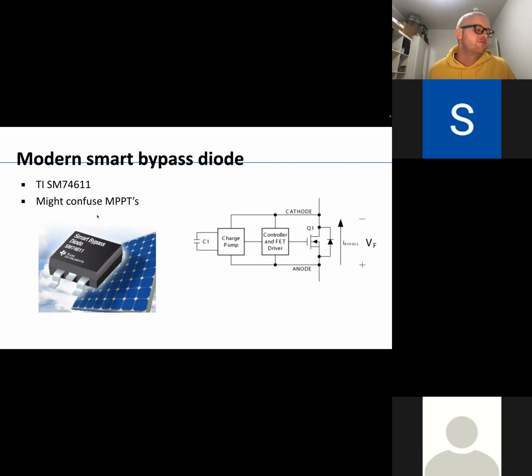So when you're tracking an IV curve and you're decreasing your voltage, making sure the diodes start turning on, you're able to track your IV curve correctly. But as you are increasing your voltage again with your maximum power point tracker to track an IV curve, you get a slightly wrong IV curve as the diodes stay on for a little bit too long.